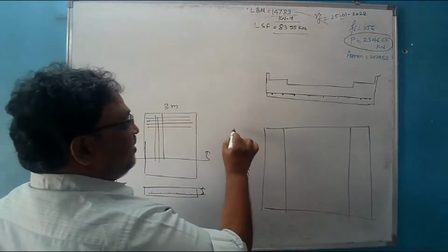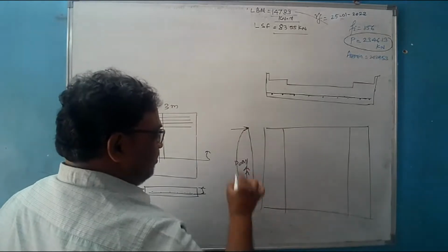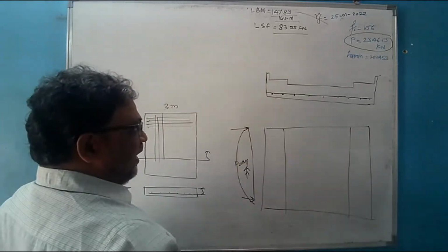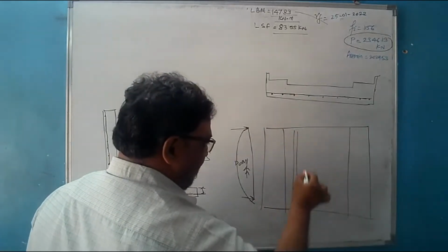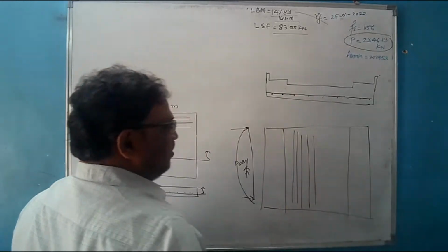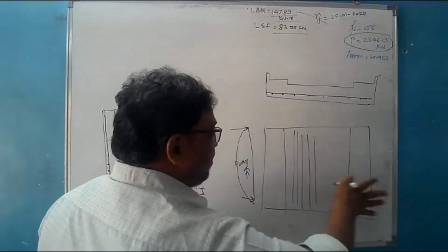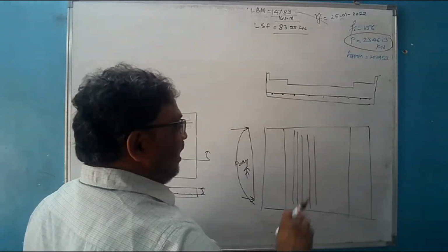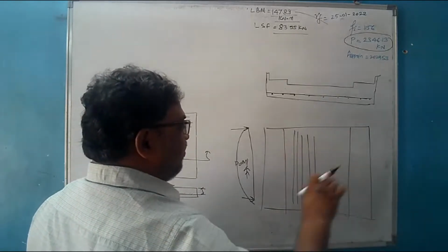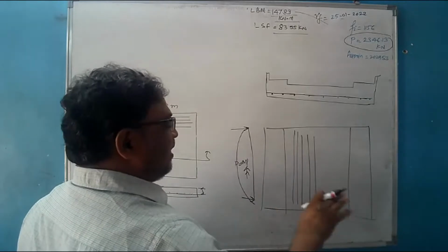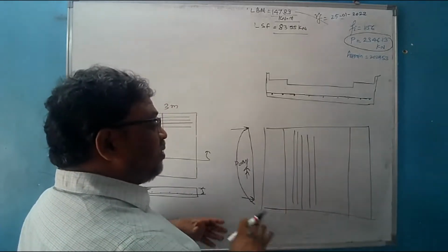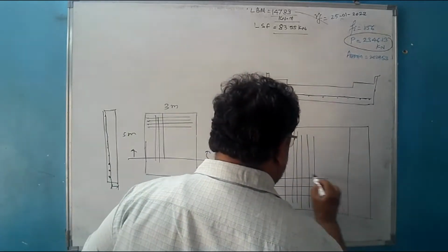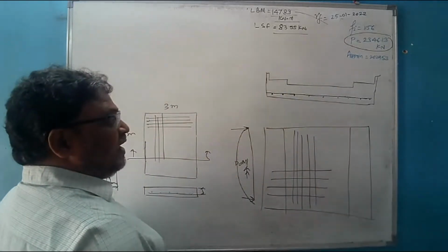दिस इज ए वन वे स्लैब, इट इज गेटिंग डिफ्लेक्टेड ओनली इन वन डायरेक्शन. तो ये जो डिफ्लेक्शन का डायरेक्शन है, जो स्पैन का डायरेक्शन है, उसमें हमको पहला रेनफोर्समेंट रखना पड़ेगा. सो द रेनफोर्समेंट वी विल प्रोवाइड हियर. लेकिन ऐसे नहीं कि हम दूसरे डायरेक्शन में प्रोवाइड नहीं करेंगे, सो एज टू टेक केयर ऑफ द श्रिंकेज, एनी एक्सीडेंटल लोड because of temperature, some stresses may develop in other direction also, and that may be responsible for the crack. To arrest those cracks, we need to provide certain distribution steel also. So we provide steel in other direction also.